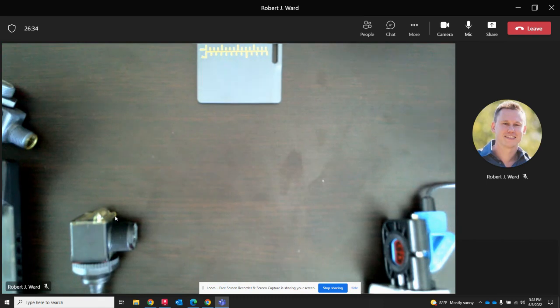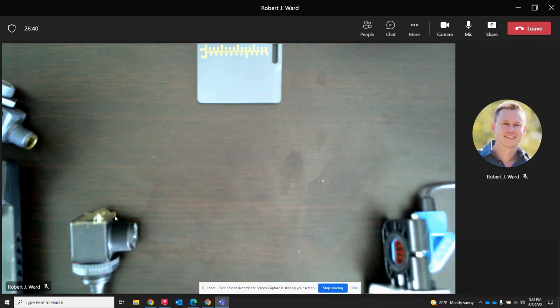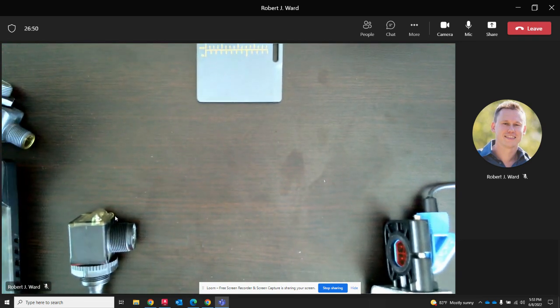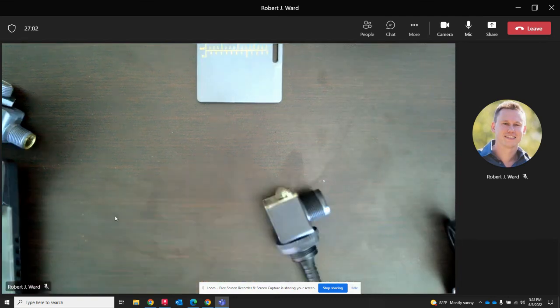And to your point, instead of that huge conical pattern coming out of a typical photo eye, it's usually nowadays going to be a laser diffused. So it's a single dot, a few millimeters wide, shooting the stretch of that conveyor over to the emitter side. So if you're trying to catch, say, the leading edge of something where you're applying a label... Right, or you want precision, right? Yeah, real precision. Absolutely. Precision is something those are good for, and that's what I've thought about.